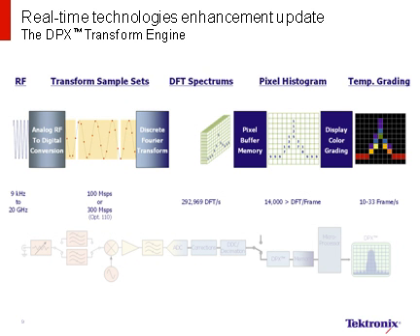Discrete Fourier transforms are processed sequentially and overlapping on the incoming signals at a rate of up to 292,000 discrete Fourier transforms per second. The sequential FFTs are put into a pixel memory buffer and collected to transfer to the display at a rate that keeps up with the incoming information. So at each time, between 10 and 33 times a second, you can transfer up to 14,000 images with a pixel memory count of the hits involved with the display. This gives you 100% probability of seeing any signal that is on for a duration of 10.3 microseconds.